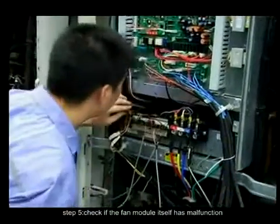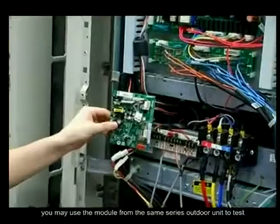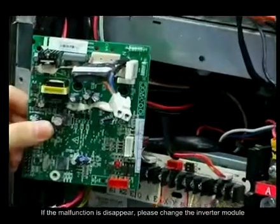Step 5. Check if the fan module itself has a malfunction. You may use the module from the same series outdoor unit to test. If the malfunction disappears, please change the inverter module.